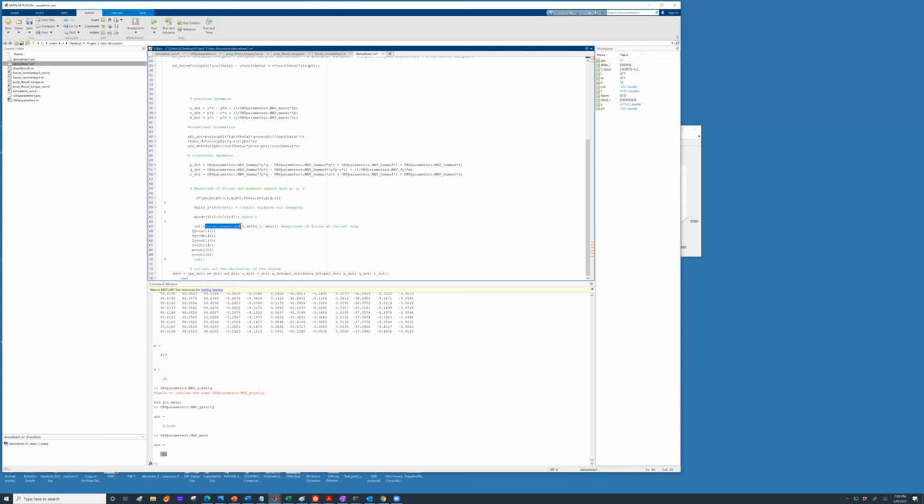Forces and moment sp takes the value of x, which is the state, and the state comes from the current state of the aircraft, which means the forward velocity, the velocity in y direction, the velocity in z direction, and the roll rate p, q, and r. So all these values are considered by this force moments function to find out the values of fx, fy, fz.